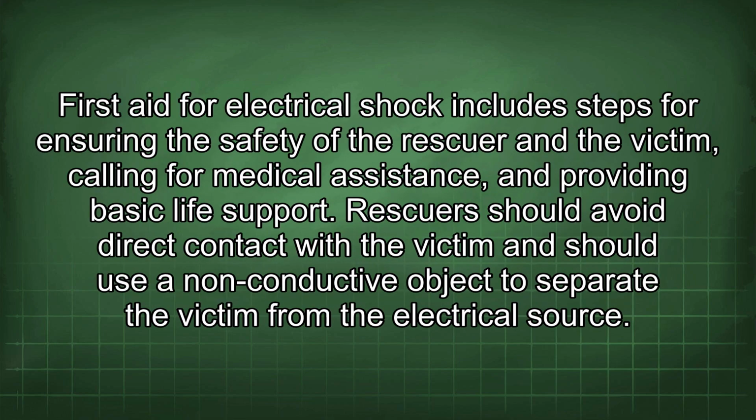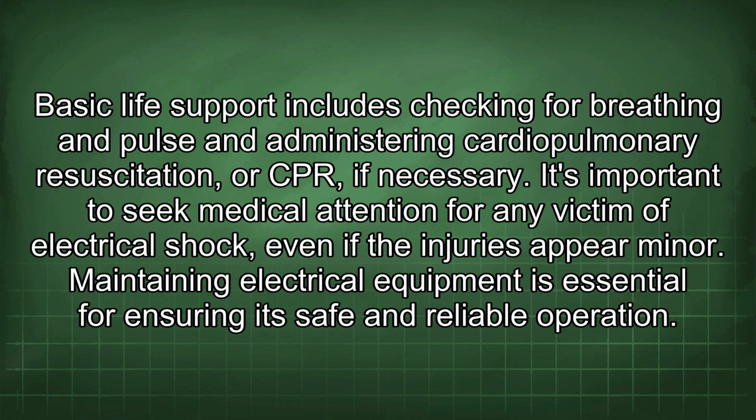First aid for electrical shock includes steps for ensuring the safety of the rescuer and the victim, calling for medical assistance, and providing basic life support. Rescuers should avoid direct contact with the victim and should use a non-conductive object to separate the victim from the electrical source. Basic life support includes checking for breathing and pulse and administering cardiopulmonary resuscitation, or CPR, if necessary. It's important to seek medical attention for any victim of electrical shock, even if the injuries appear minor.